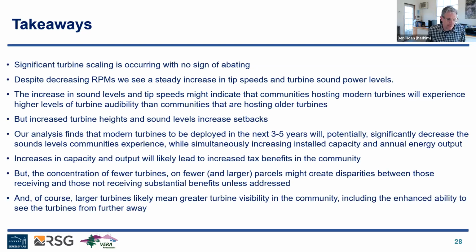I will also note that the FAA, the Federal Aviation Administration, has different requirements for lighting for turbines that are taller. So, for example, an additional light might be required on the nacelle for turbines greater than 500 feet. And turbines that are greater than 600 feet, 650 feet will actually need a light or a set of lights along the tower as well. So a lot more lights will be visible at night.